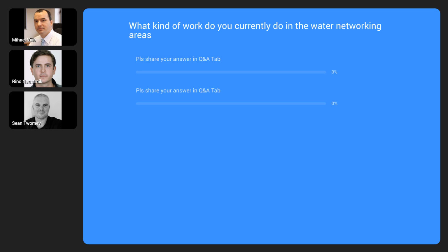And what is a great thing is the possibility to communicate with WaterGEMS, because for water distribution networks we can both import and export the EPANET INP file, which can be imported to and exported from WaterGEMS as well. And regarding the storm and sanitary networks, we can export the EPA SWMM INP file, which can also be imported to SewerGEMS. And in the next version, which will come out by the end of this year, we also developed the possibility to import the EPA SWMM INP file, which can also be generated in SewerGEMS.